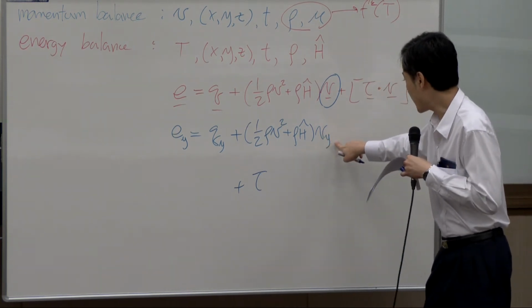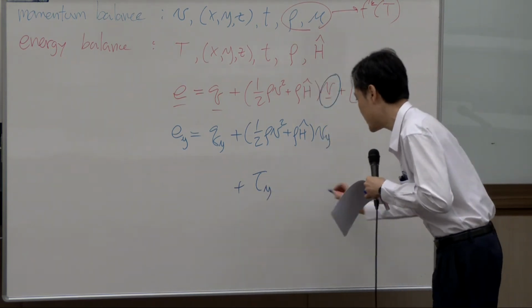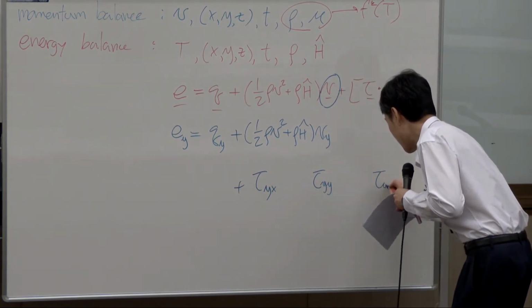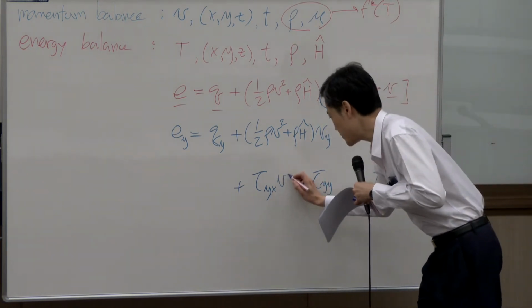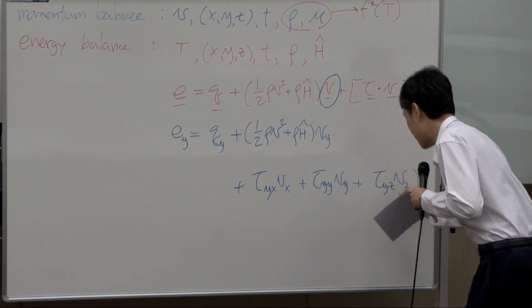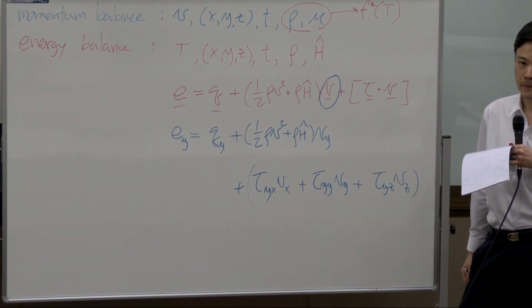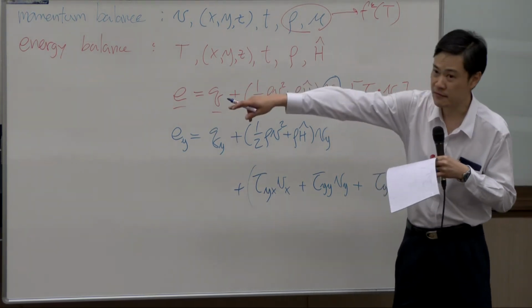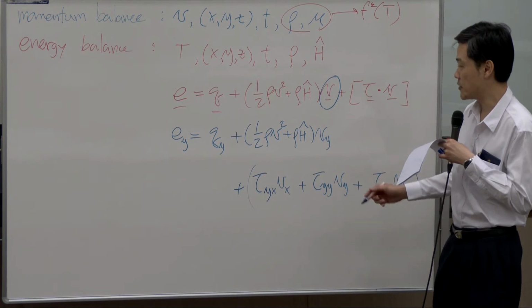when you write for Y component, the first subscript for tau should always be Y. So you start with Yx, Yy, Yz. Okay? And this V, which would vary from Vx, Vy, Vz. So this would be the flow work term. Okay? So before plug everything here in the differentiation over there, you just have to remove which term will be 0 first.